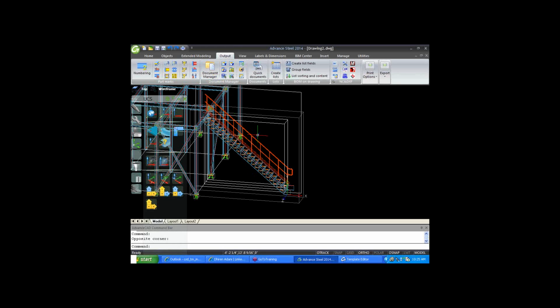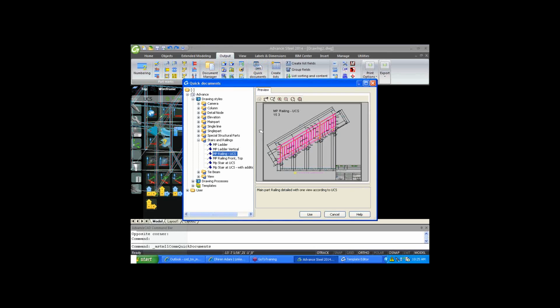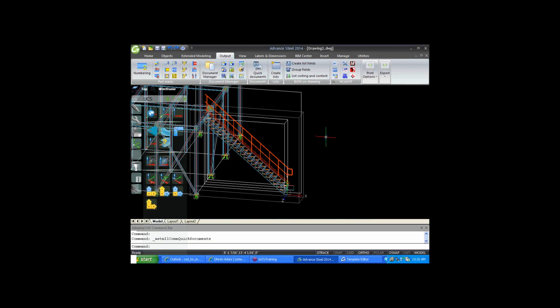But while generating this piece as an assembly using this dimensioning style, you have to cancel the old main part and single parts created within the model, and so you will be able to use those two drawing styles here. Okay. So even though it created that assembly already, or it created the parts to the assembly, now you have to still go back in there and delete that drawing out.